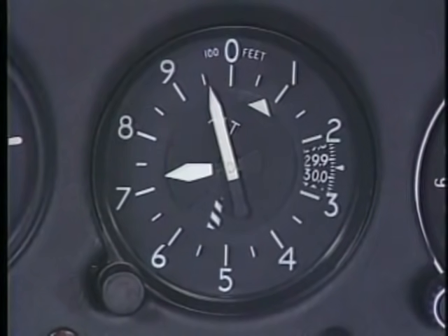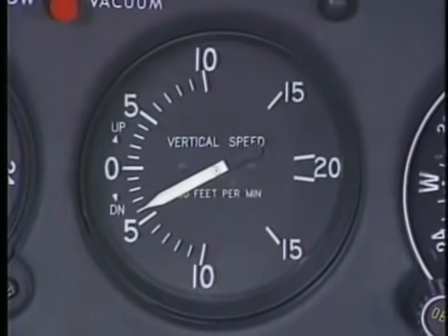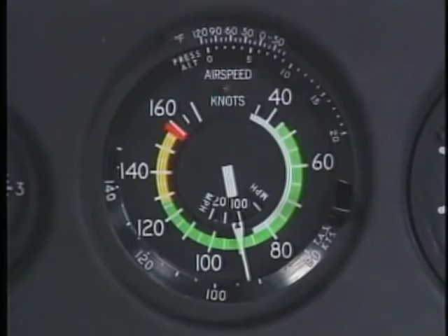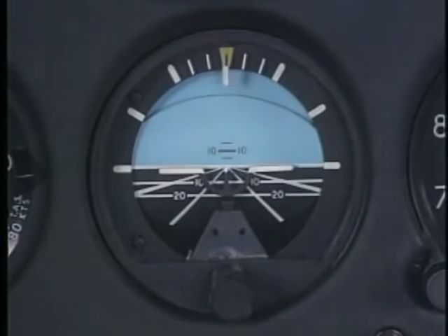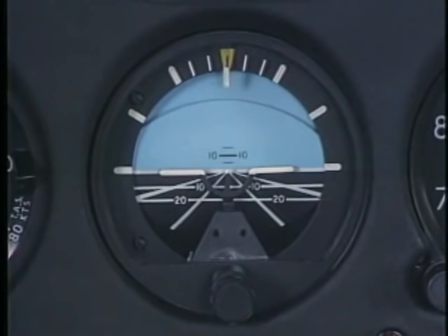If your altitude starts to change, look at the VSI to determine the rate of the change. A small rate change will only require a minor correction. You should also check the airspeed indicator to see how the pitch change has affected the airspeed. If the airspeed is extremely fast or slow, you'll have to make a larger correction. When you have determined that a correction is necessary, stop the movement by adjusting the pitch attitude slightly. Then make the necessary adjustments to return to your desired altitude.